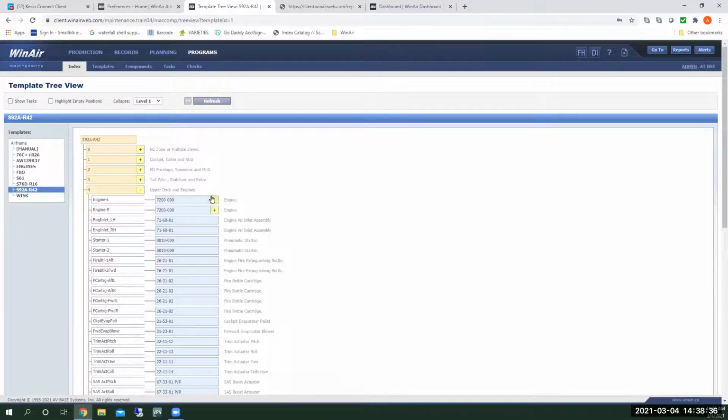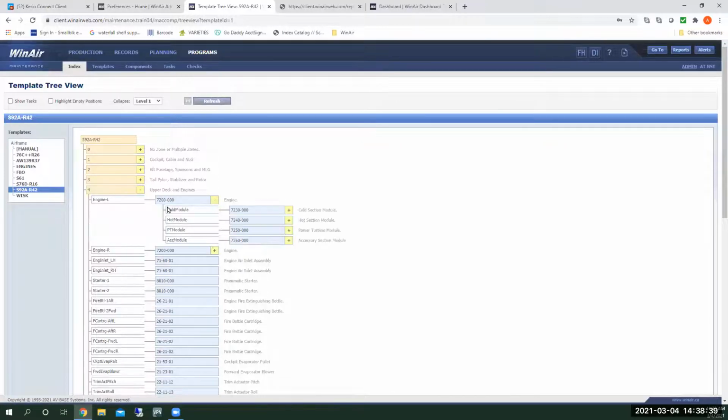Why this is important within aviation is these parts may be removed at some point in the life of the airframe, may go out and be overhauled or repaired, and then returned either to this operator or to another operator. So these need to live an independent but related life to the aircraft, where they accumulate hours and cycles from the aircraft, but all of that information will travel with that component and subcomponents as it moves either within the aircraft fleet of an organization or moves outside due to, as I said, overhauls or repairs or what have you.